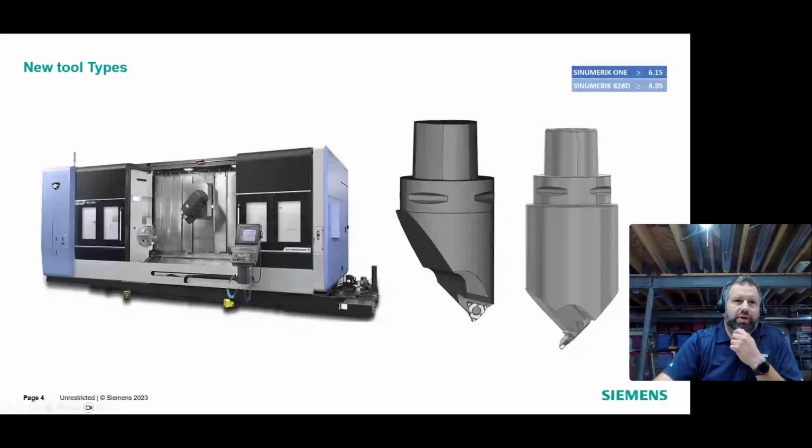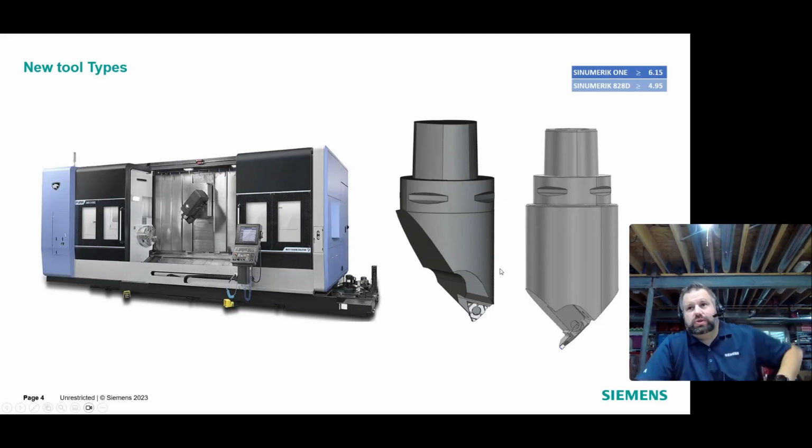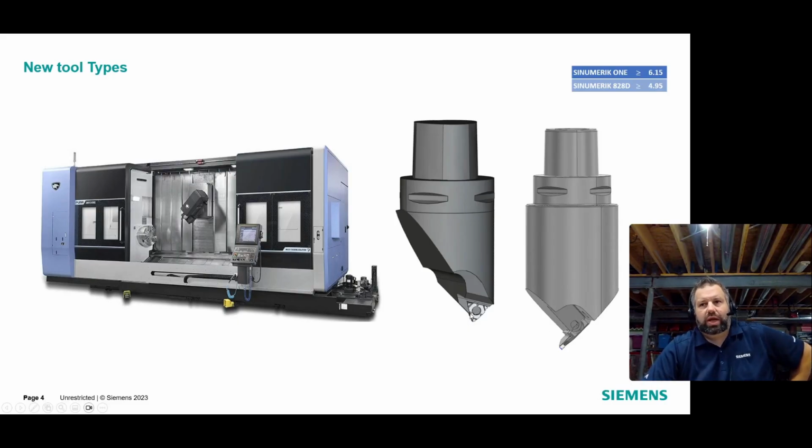So having it at 45 degrees really gives you the capability of not colliding with anything. Tooling manufacturers have developed some nice tools that give you the capability of having 45 degrees, right? So even with threading tools, grooving tools and cutoff tools, now we can get really close to the chuck and not have to collide.